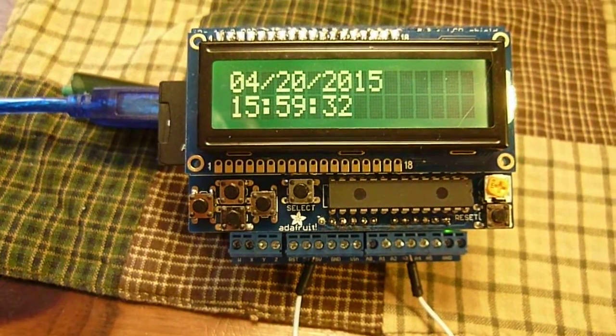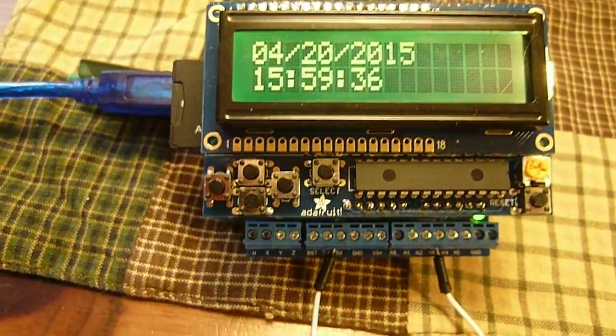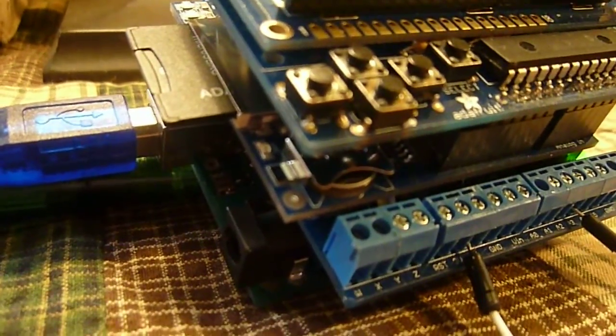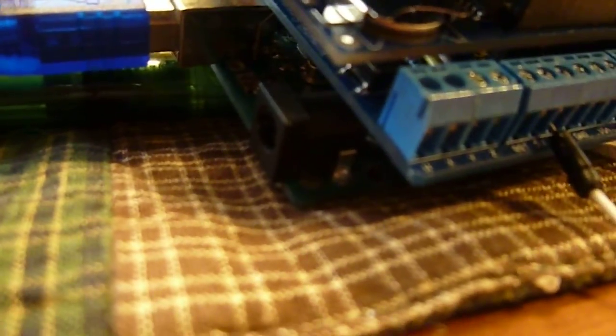Today we're talking about our data logger for solar and wind off-grid applications. Now we have a LCD keypad on top here with some control buttons. Underneath that we have a real-time clock with SD card module. Then under that we've got a screw terminal shield with prototyping space where we have our voltage dividers. And then underneath that we have an Arduino Uno.